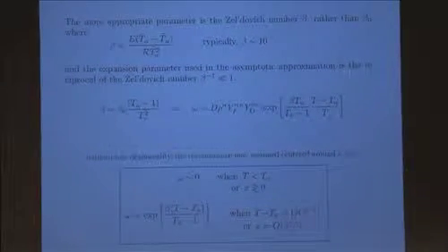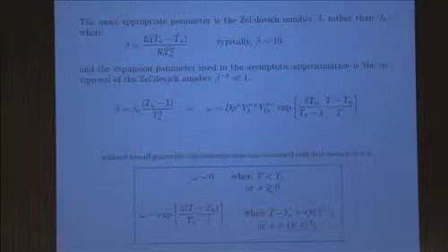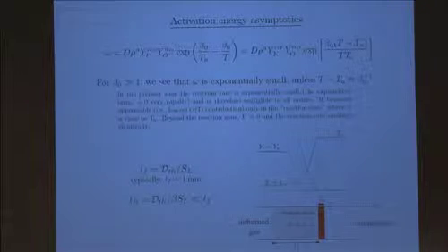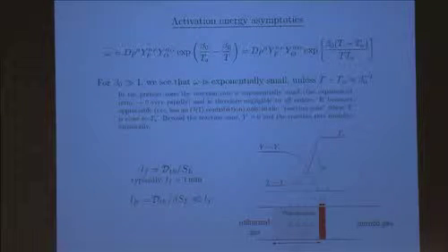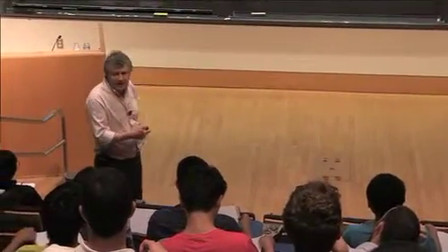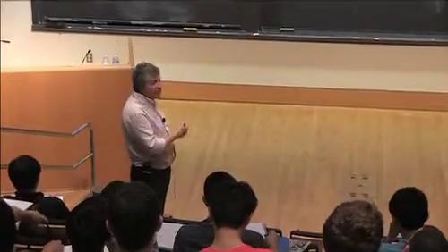And this is essentially in words what I have used so far, this parameter beta naught, which was defined as the activation energy divided by the unburned temperature. Now, it turned out that after you carry on the analysis, the more appropriate parameter for expansion turned out to be this quantity.